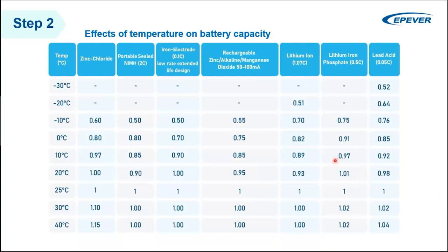It's important to note that the loss of capacity also depends on the charge and discharge rates. So it's important at which rate you are charging your battery. That's why most chargers have a temperature sensor in the system, and it's capable of finding the best charging current based on the temperature of your battery.